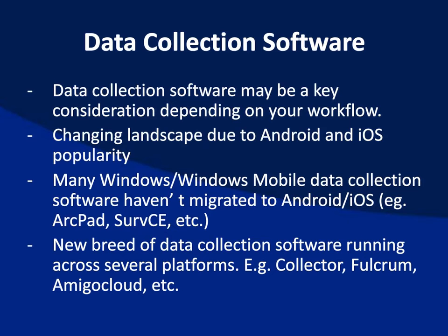And then lastly here, there's a new breed of data collection software running across several platforms. Esri's Collector runs on Android and iOS. It's a pretty lightweight client piece of software now, but they're moving along trying to make it better. There's products like Fulcrum and Amigo Cloud that are, again, subscription-based cloud apps. You can use them in standalone mode, so you don't have to be connected all the time, but eventually it syncs up with the database in the back office.